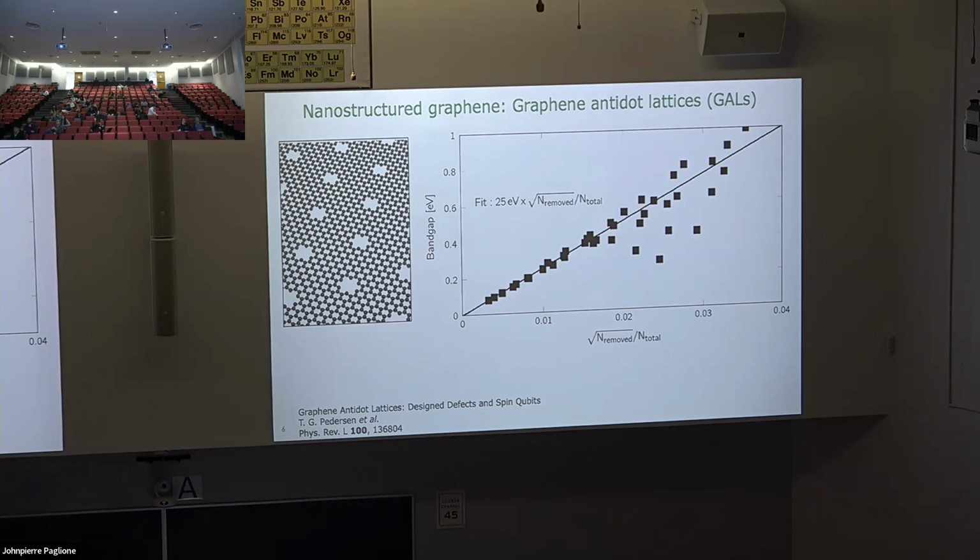So there was a lot of really interesting work in this direction. It's easy to do these things on the atomic scale if you're just doing calculations. But because graphene had so much potential as a next-gen electronic material, there was a lot of effort trying to realize this in practice. And this is something you can do with 2D materials. You can go in and easily remove the atoms, and you can easily go in and change the local electric environment because all of your bulk is exposed immediately. It's not like a 3D material, where having a nice periodic potential throughout something that is a millimeter thick is just not feasible. And in the same way, making nice arrays of holes or patterning your material in some way is much, much harder to do for 3D materials. So 2D materials were really a game changer in the field of band structure engineering beyond just theory.